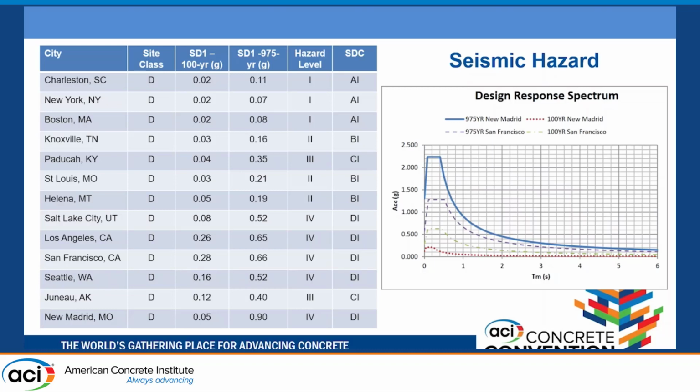So that was set in place for ordinary bridges. Now, when you look at something like the Cape Girardeau suspension or cable-stayed bridge, you would probably want something with a much lower probability of exceedance in the 75-year life. So you might then use, and this is what's typically been done, a 2,500-year design hazard.